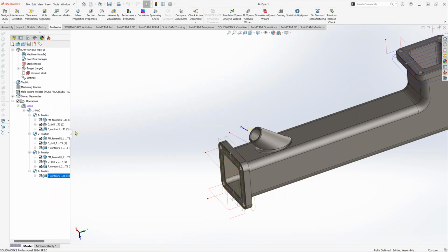I still didn't show some parameters, like how to define the ratio, how to define CW and CCW, because we are limited in time. But of course, everybody can make this assembly of an angular head for your machine and use it for your parts cutting and save a lot of time and complex fixtures. You can also simulate it in machine simulation to understand what's going on in the machine, and if you don't have that, you have a machine preview, so you can estimate what happens.